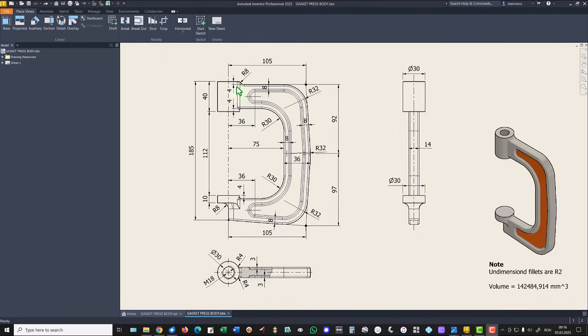We start by creating this contour and we apply extrude on 14, symmetrical. We use dimensions in the drawing. For instance, I have to place a dimension between this line and this point. I'll use 185 dimension in the drawing minus 4 dimension in the drawing.